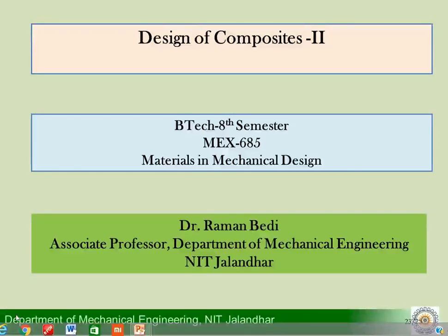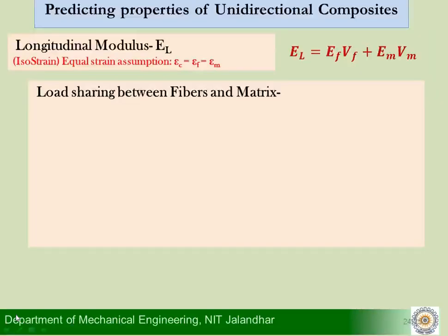So, students, welcome back to this course on materials in mechanical design. In my last two videos, we have seen that we were able to predict the longitudinal modulus of the composite, which we say is EL, through this expression: EL is nothing but EF VF plus EM VM, where all these variables have their meanings, which we have already understood clearly.